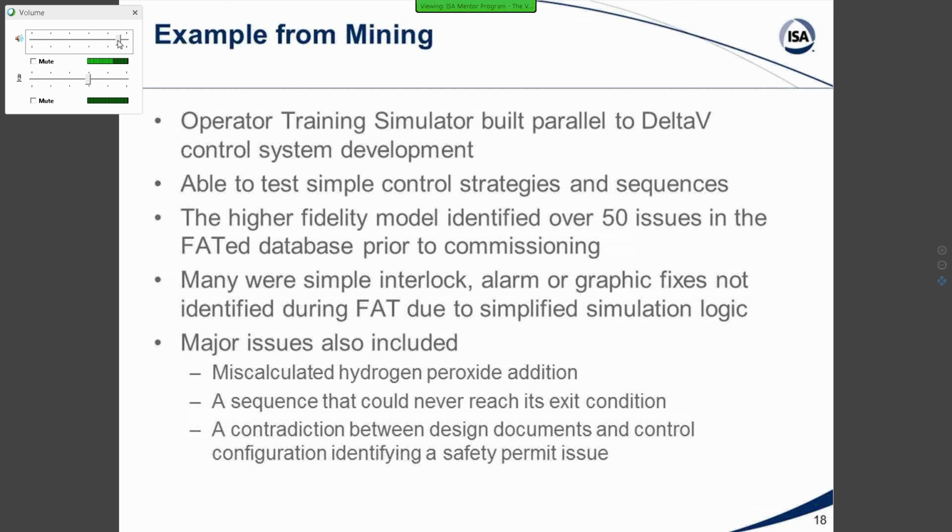And there's the things that you didn't see. For example, the initial simulation they were using for the FAT had all of the flows set to constant non-alarming values. That's not really a realistic situation, and they had alarms that would go off if you had zero flow. So essentially, if everything was turned off, your entire plant was alarmed, which there wasn't a real reason for, and actually the normal running condition was to have the pumps off because it was a batch operation.